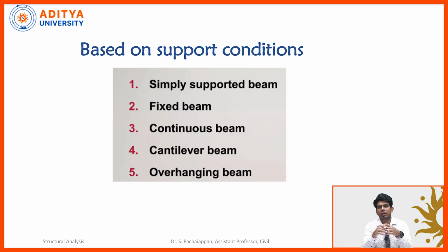for example, in the earthquake resistant design of structures, we never want the structure to be completely anchored to the earth. Otherwise it will transfer the ground acceleration to the structure. Finally, the structure will deform a lot and deteriorate a lot. We never want that. So, we do base isolation by using different types of mechanisms, which is nothing but keeping the structure on roller supports. So, it is based on the application, but in general, we never want the structure to move.